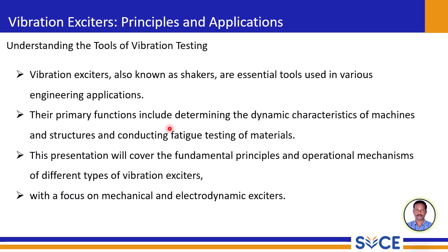First, vibration excitators allow us to determine dynamic characteristics of machines and structures. Think about it, how a bridge responds to wind or how a car chassis behaves on a bumpy road. These are dynamic characteristics, and shakers can help us to determine and understand them. Secondly, they are crucial for conducting fatigue testing of materials. By subjecting materials to controlled vibrations over extended periods, we can assess their durability and predict their lifespan under real